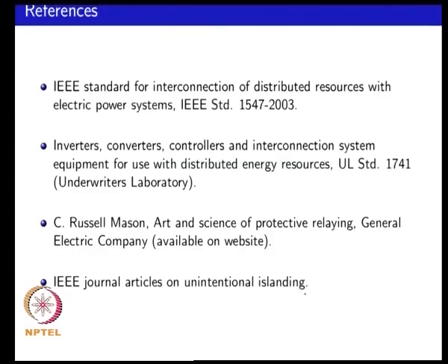So, for references related to these issues, you have IEEE standard 1547. Here this is a recommended standard. It is just a recommendation, it is not enforceable, but then you have similar issues that are shown in things like UL 1741, which is an Underwriters Laboratories standard.